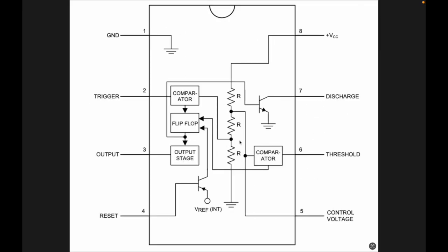Diagram of 555 timer IC. The 555 timer IC contains 8 pins. The 555 is a highly stable device for generating accurate time delays or oscillation. Additional terminals are provided for triggering or resetting if desired. For astable operation as an oscillator, the free running frequency and duty cycle are accurately controlled with 2 external resistors and 1 capacitor, which we are going to do in our second experiment with IC 74LS163.